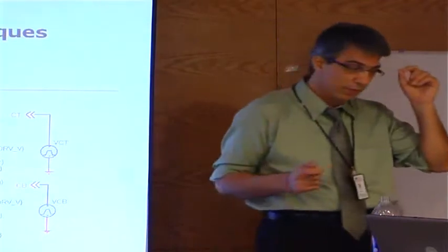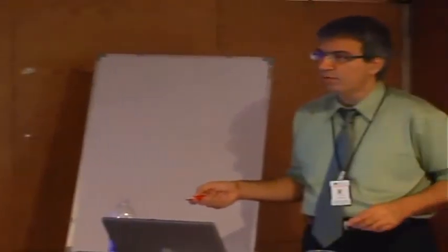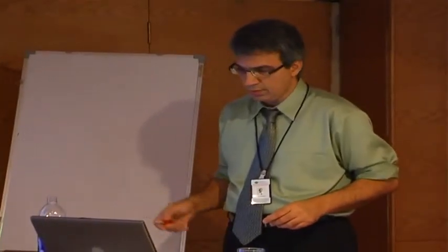In this case, we have used a motor from Moog, the manufacturer. We have used an odd frequency, 133 hertz, as the rotation frequency. So the period is 1 by frequency, 1 by 133 hertz.